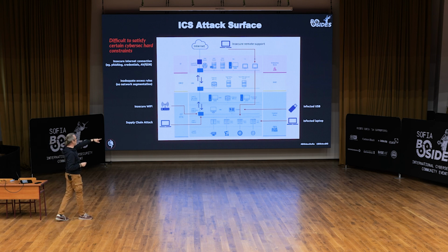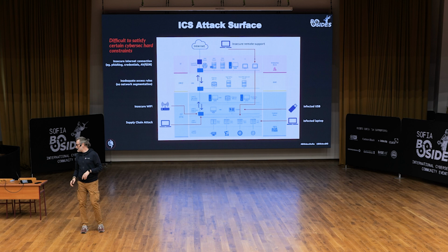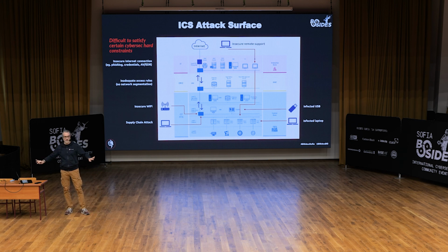Another big problem is infected laptops. I'm a Barilla guy. I'm the maintainer of the Barilla BI. I'm the programmer of the PLC. I use my PC to change the configuration parameters inside the OT plant. But I use my PC also for email, web surfing, searching, and so on. It's absolutely common. The same PC, the same laptop, is used in both domains. It's very difficult to find a customer that uses separate PCs or a virtual machine inside. What's a virtual machine? For OT guys, it's something strange.